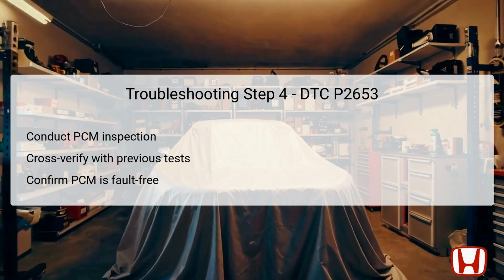By comparing the results of the earlier diagnostics against the expected behavior, it can be determined if the PCM itself is faulty. To confirm this, further checks to validate the integrity of the PCM circuits and logic are essential. Only after confirming that no external issues exist can the PCM be deemed the cause of the DTC P2653, after which repair or replacement may be necessary if it's found to be malfunctioning.